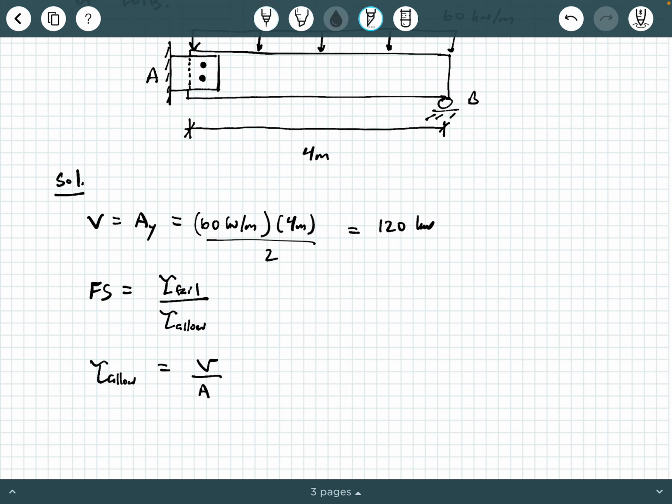bolt. Now, what is this shear force, this little v? Is it the exact same as this capital V that I wrote a few steps back? Not really, because we have multiple bolts. This little v right here, I'm going to rewrite as that capital V divided by the number of bolts, and then that is still divided by the cross-section area.